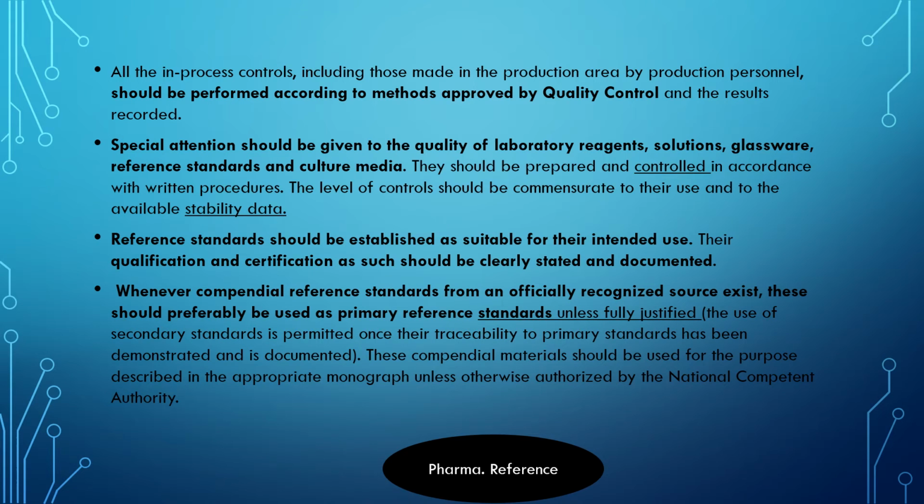All the in-process controls, including those made in the production area by production personnel, should be performed according to methods approved by quality control. Special attention should be given to the quality of laboratory reagents, solutions, glassware, reference standards, and culture media. Reference standards should be established as suitable for their intended use. Their qualification and certification as such should be clearly stated and documented.